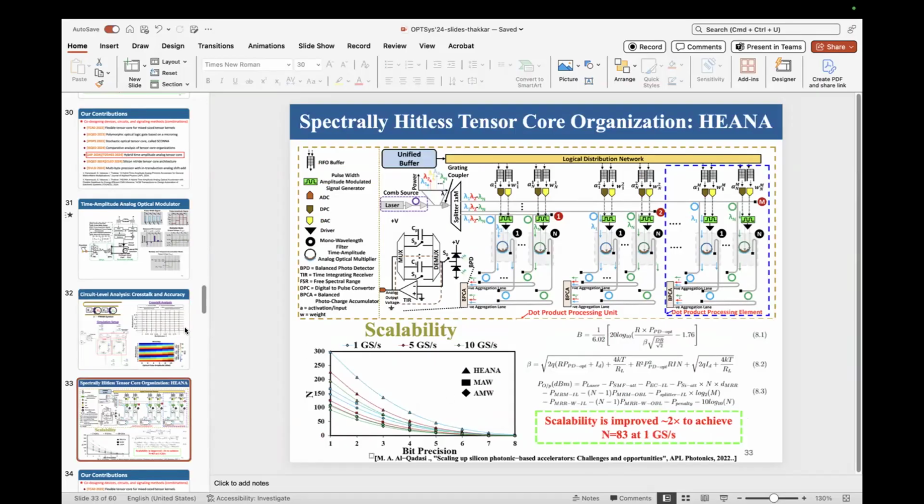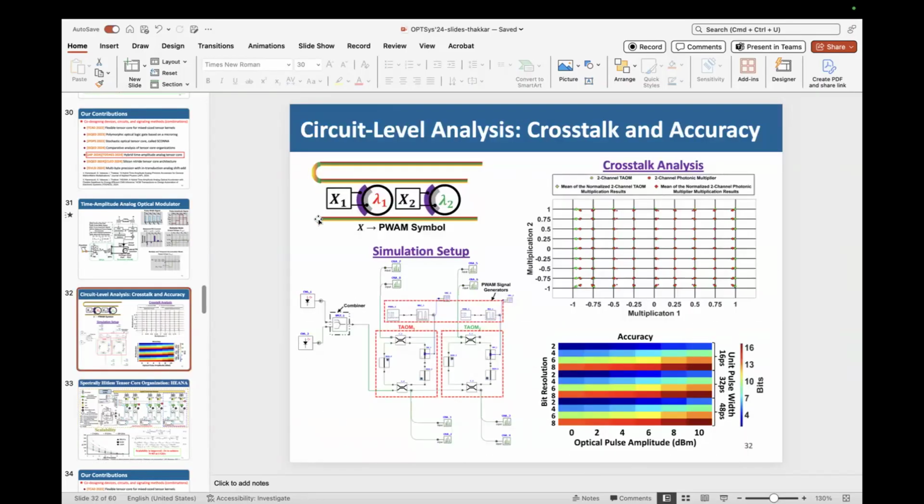The main idea, even in this domain, is that every signal will have to pass through fewer microrings in this sort of organization, because there are only 2 microrings. Versus the other case, when you have separate modulator and weighting elements, you will have 4 microrings: 2 in band and 2 out of band. In this case, it's 1 out of band and 1 in band. That significantly reduces crosstalk, power penalty, insertion loss and everything. And that is what gives us the advantage.